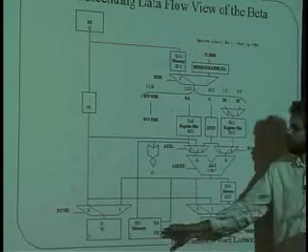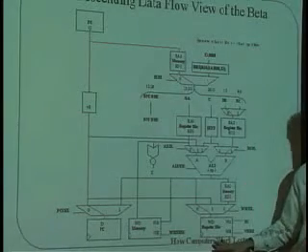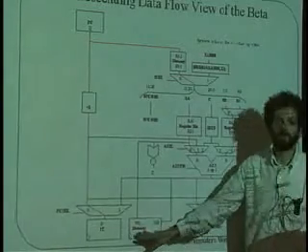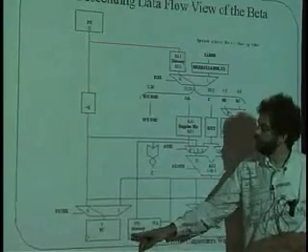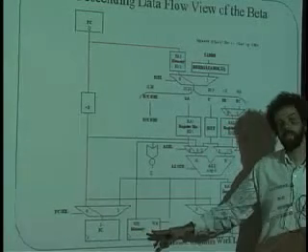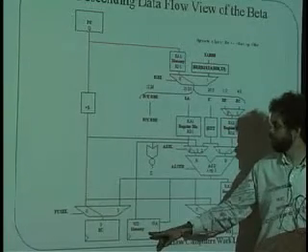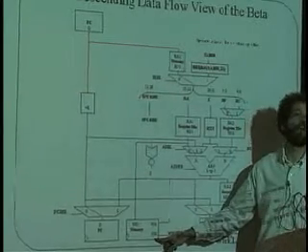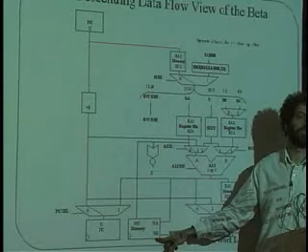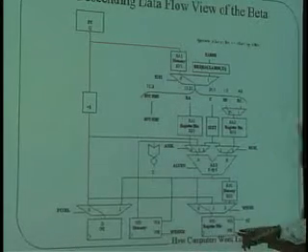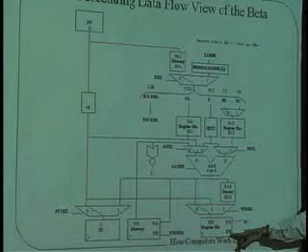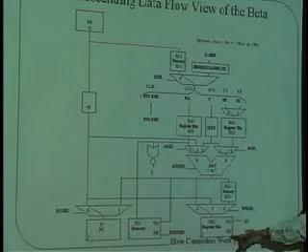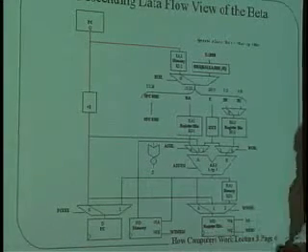On the other hand, we have two other portals here for writing, one being a portal into the register file, the other one being a portal into the big slow memory. And when the clock goes off here, sometimes we're going to write into the big slow memory and sometimes we won't. That's determined by whether or not the WE here is high or low, whether it's a 1 or a 0. In the same way, whether or not we're going to write into the register file will be determined by whether the WE here is high or low when this clock goes off.